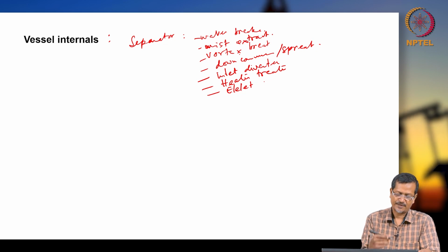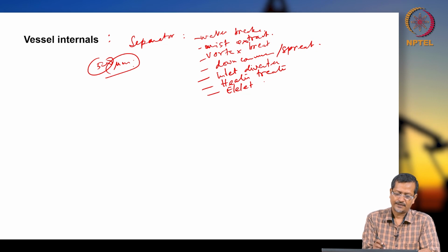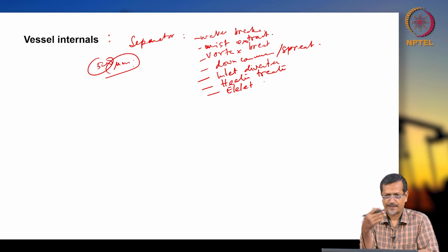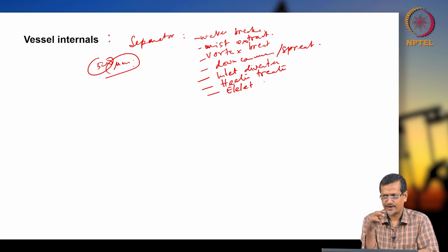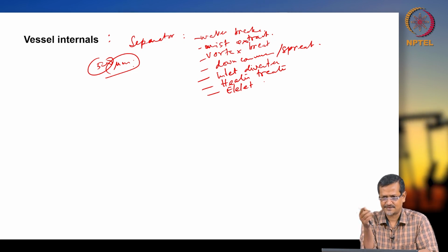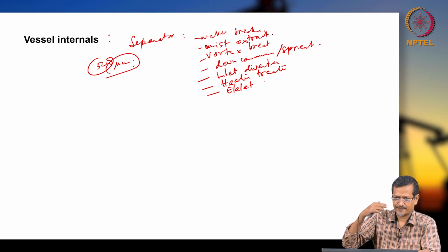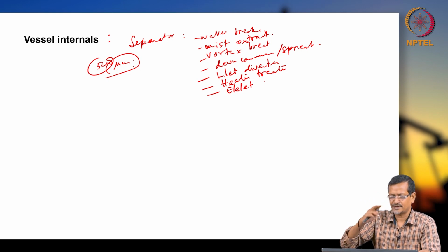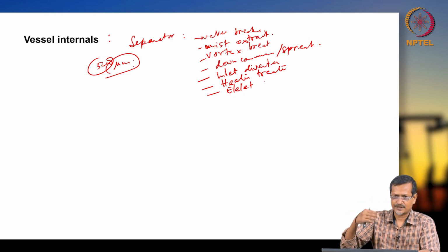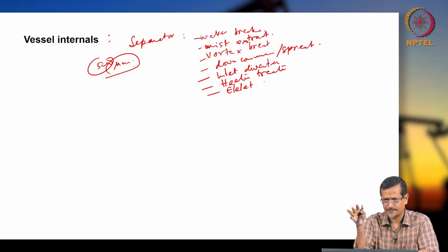Water droplet size is normally 500 microns. Whenever we start calculating, initially it will be 2-phase separation, liquid and gas, gravity settlement. When we consider liquid and gas settlement, normally we consider around 100 micron particle size, so the liquid particle will be 100 micron. But when we are separating oil and water, in 3-phase separation, the water droplet size will be 500 micrometer or micron.